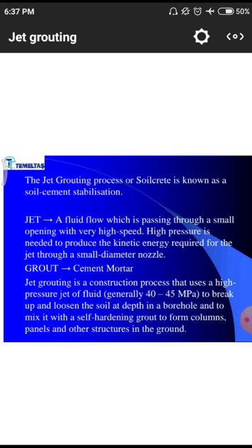Why? Because these kinds of jets are used for the production of electrical energy. Normally, this jet of water is pumped onto the vanes of a turbine, so that due to the pressure exerted by the jet, the vanes rotate. Due to those rotational forces, the turbine generates electric power, converting kinetic energy into electricity. So here a jet means simply the force exerted by the flow of fluid.